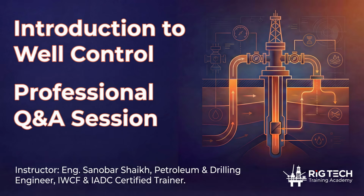So the well design is done in such a way that we know what pressures we are going to encounter in our well, and at what depths we are going to have that pressure. That's how our casing is also designed, at what depth our casing should be set. If we have a different formation, we will set another casing there. We will drill with another drilling mud and set a different casing. If there is another type of formation, we will set another casing like this. So it comes under well design and casing setting depth.